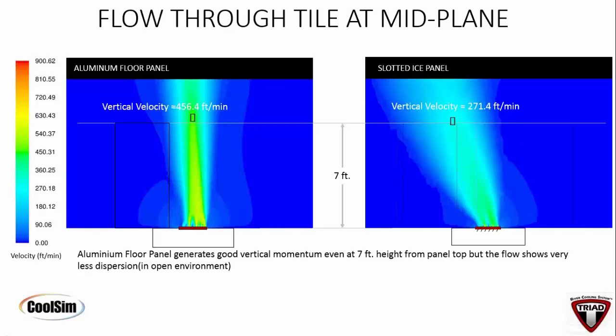All right. If you have two tiles consecutively placed in the floor along the laminar path of air under the floor, how would the airflow of the second tile be affected? Well, it would have a similar behavior, I think, in that it would still grab some of the air going by and pull it up. I think it would behave pretty similarly to the one in front of it. The fins redirect, and so the redirection is going to take place no matter what because they're grabbing the air under the floor and redirecting it, I think. Is that what you've seen, Gary?